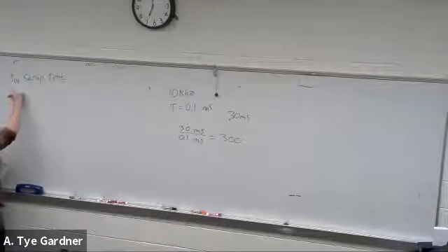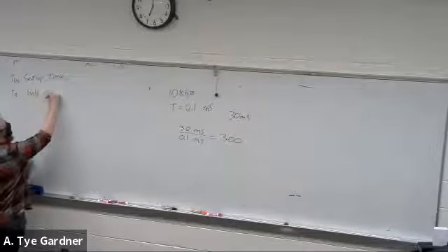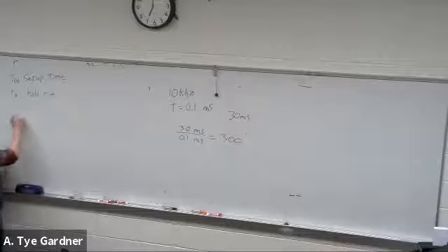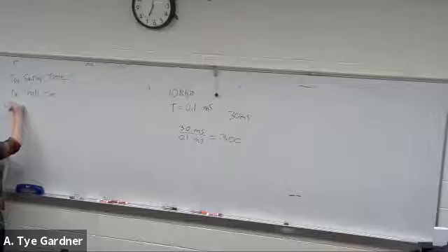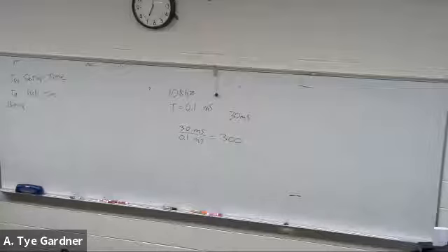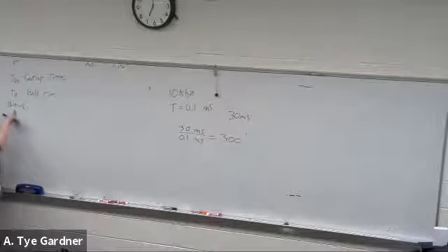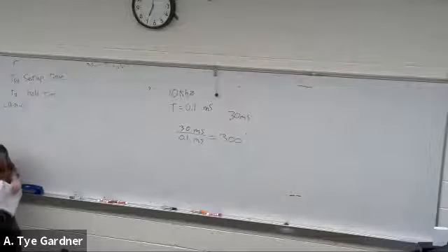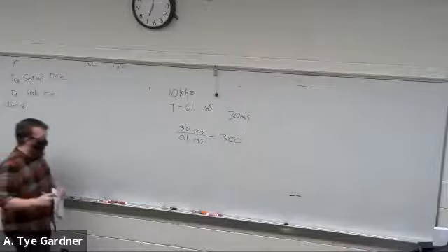They also have TH, hold time, and, well, this is how I'll write it, I'll go check the book, Clock to Q. What that means is the amount of time between the rising edge of the clock and when the output Q updates.